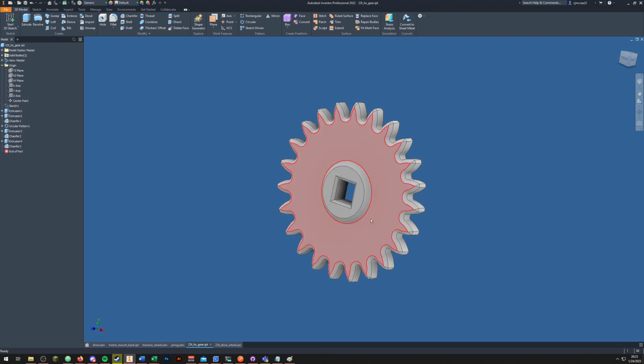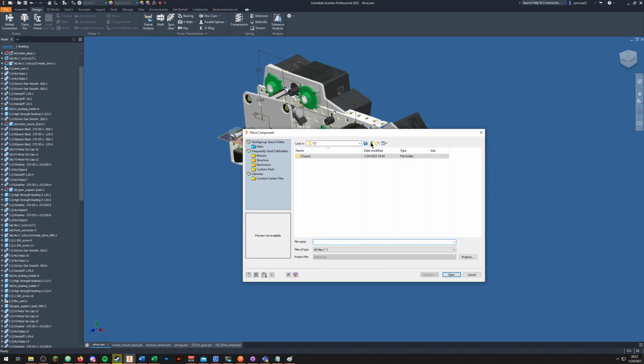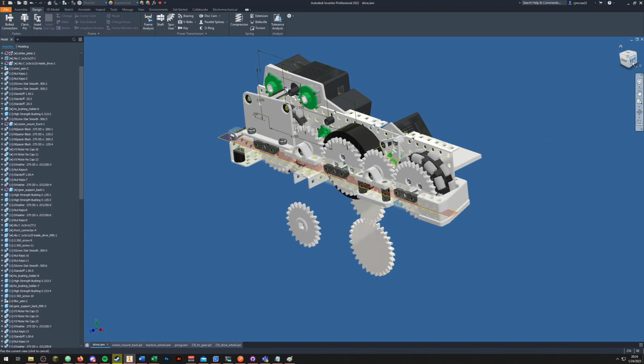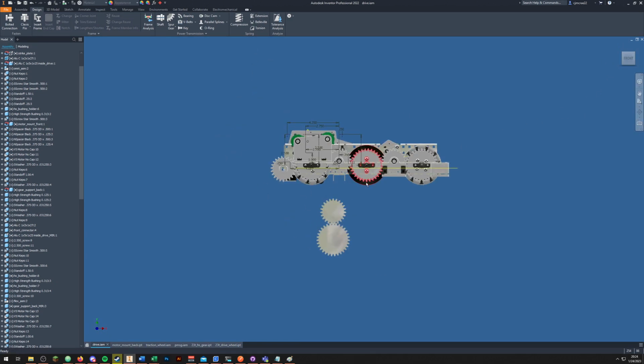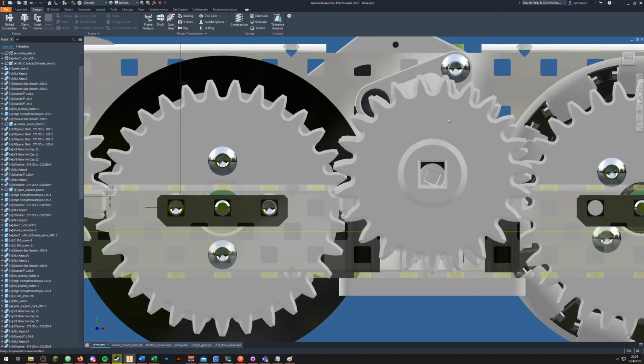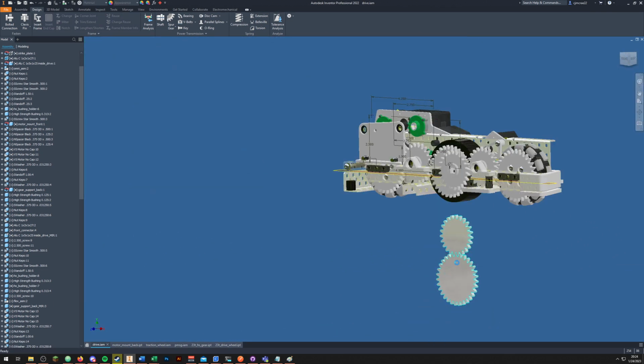And it's important that I mention we shouldn't reuse these gears for different purposes because it was made specifically with one center to center distance in mind, working specifically for this. So if you were to change things around or make a different subsystem, this gear would not necessarily work. I'm going to go ahead and grab the gear here, place it into our assembly, and we can see that it's effectively identical to the one that we've designed. So that's the first gear. Again, we can go back and do that for the second gear.